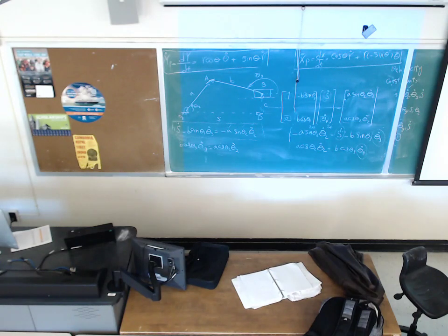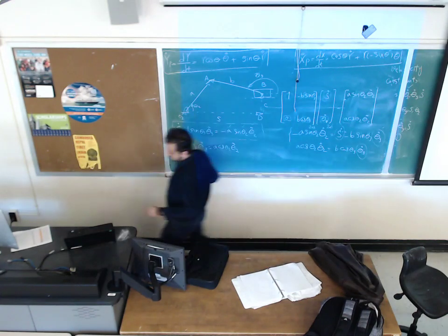Define matrix B as -6 and 8, and then in MATLAB use A backslash B. It's going to give you the answer of the system of equations.